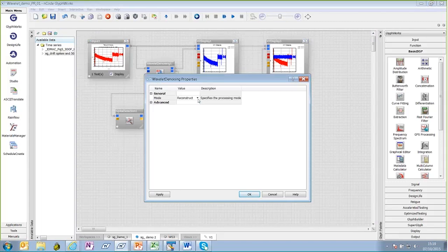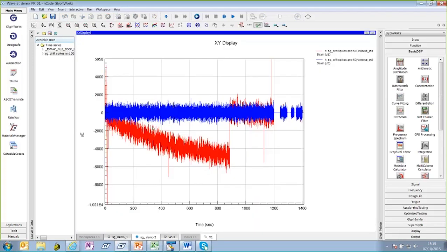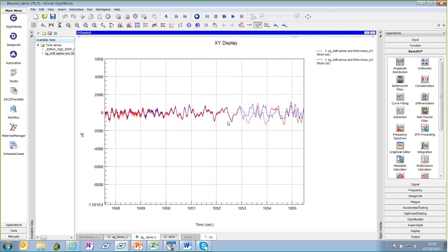What this does is look for a set of channels with the appropriate metadata telling it that these are wavelet levels. It will take those automatically and reconstruct that data. So at this point, we've taken out the wavelet function that gave you the drift on this signal, and also some of the spikes in the wavelet domain, while still maintaining the good signal you want.